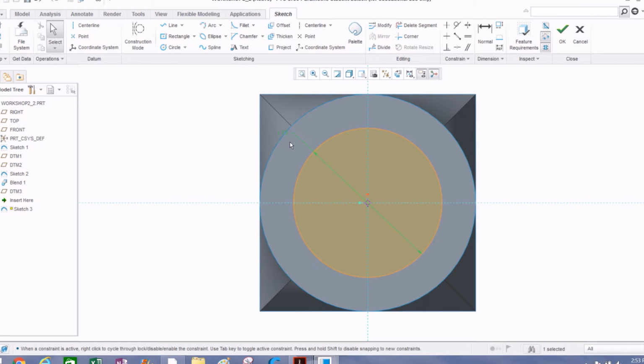Now I'm going to give you a hint on this just because I don't want to have to go back and correct it. The first circle is broken into 4 sections. This is going to be 2 sections again. So unfortunately, we're going to have to click the center line tool and create those sections. So click center line, center of the sketch, draw off to the side, center click once. Looks like we'll have to dimension this guy. Actually it's down there, but you can also click dimension from the center line and call it 45.